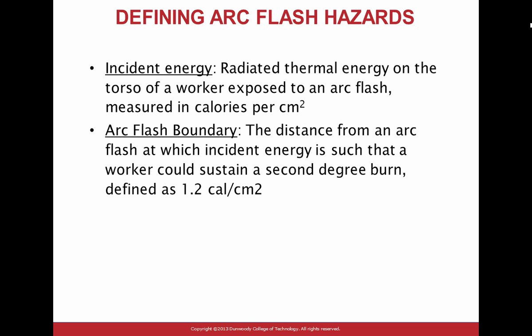Now we're going to go to the arc. The arc will force you to do what? To put this one on, because there's a big ball of fire coming at the tip, and use other things. Okay, here's the arc. Incident energy. They call it incident energy, guys. Radiated energy on the torso of a worker exposed to an arc flash, measured in calories per centimeter squared. The way they measure it, I think it's 18 inches. They assume you're working on a piece of equipment and your chest is 18 inches away from the panel while you're working, and the energy is going to land right on you.